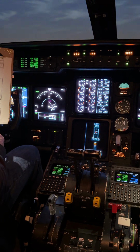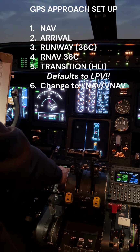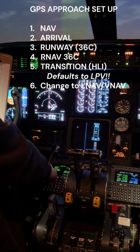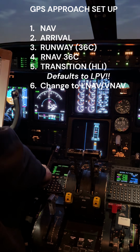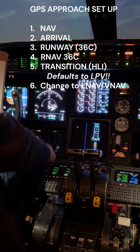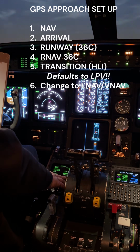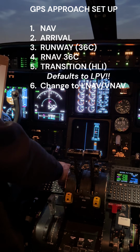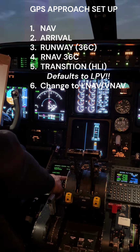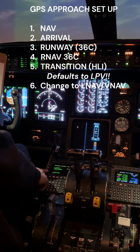So the first thing we need to do is set up the approach. So we want to go nav, arrival. We want to choose runway 36. We want to choose RNAV to runway 36. The transition is HLI, which is where we're going now. And then we can hit arrival. But the FMS is going to default to an LPV approach. We don't want that. So you need to line select to right here where it says RNAV minimum. And you need to switch that from LPV to LNAV VNAV, which we will do here.